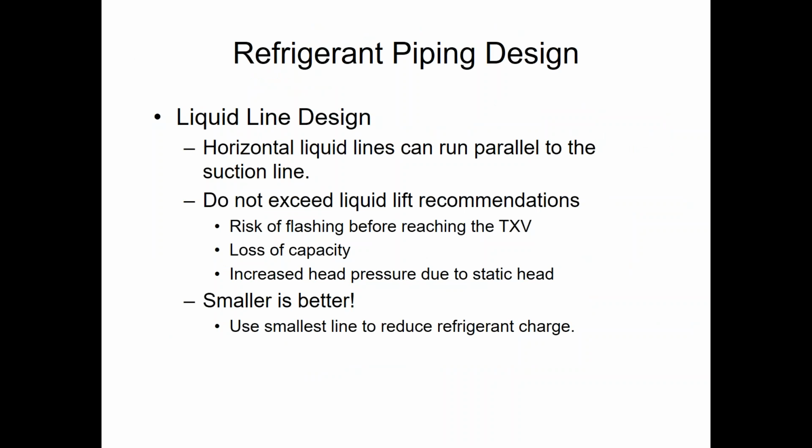All right. So let's talk about the liquid line a little bit. Liquid line designs, typically they have the same routing as the suction lines. Things we have to watch out for on liquid lines, and they're certainly way more forgiving, liquid lines are. They have no problem entraining the oil. Our velocities aren't as big an issue, but you can get into trouble with oversizing. You got to be conscious of liquid lift.